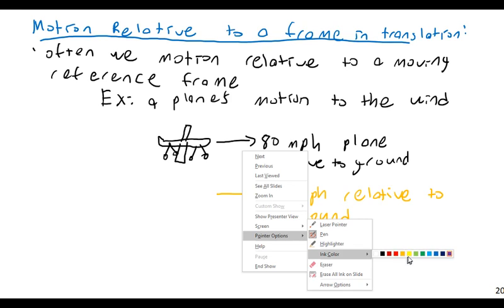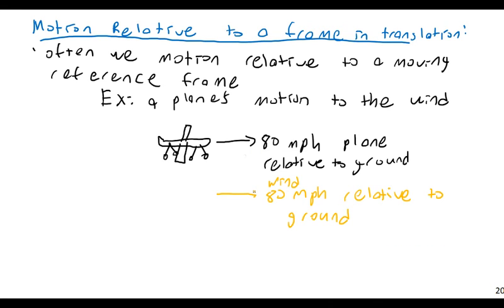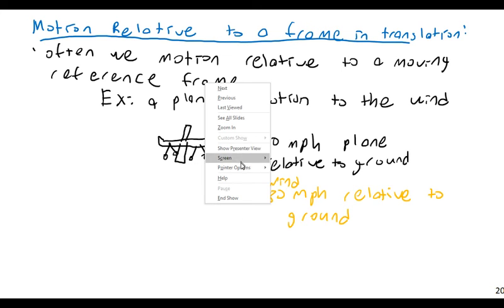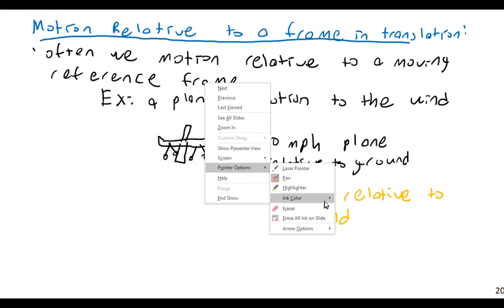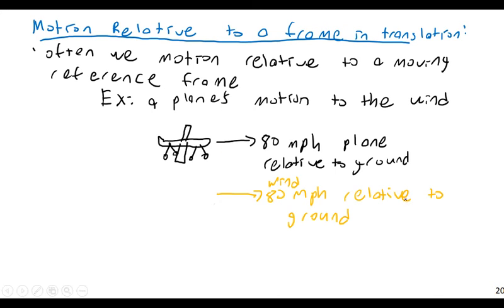What if this thing, so that would actually give it lots of lift. Let's go the other way. Sorry, I don't want a headwind. I want an 80 miles per hour tailwind. Right? So what happens there? The plane falls out of the sky. Why? Exactly, it's generating no lift. Lift comes from the relative motion of the air with respect to the wings. Lift is produced by relative motion, by air flowing over the wings.